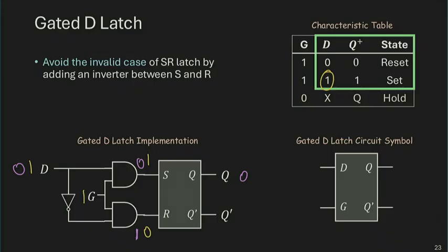Okay, now I'm essentially achieving the same functionality with one less port. It's a bit of optimization. And in reality, we use this kind of D component, D latch, and later we'll see a thing called D flip-flop, a lot more commonly than SR latch and SR flip-flop.